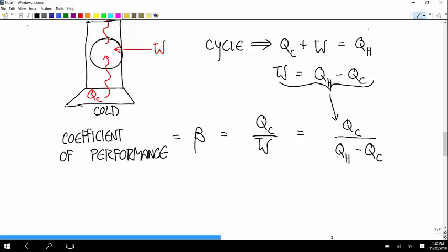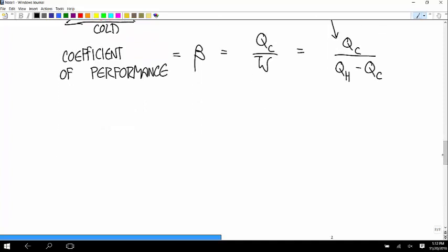But we're going to see that even for a power cycle with no irreversibilities, so frictionless and everything at perfect efficiency, there's a limit to the efficiency you can get, just depending on what your boiler temperature is and your condenser temperature is. It's sort of a surprising result, but we're going to see that. Any other questions?